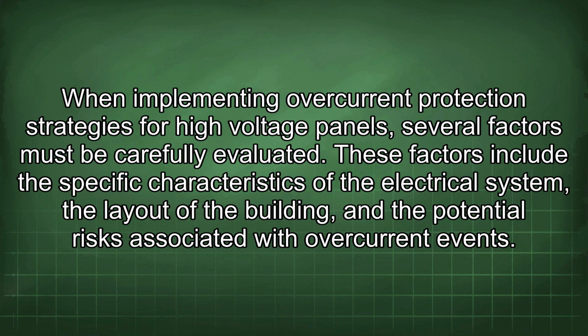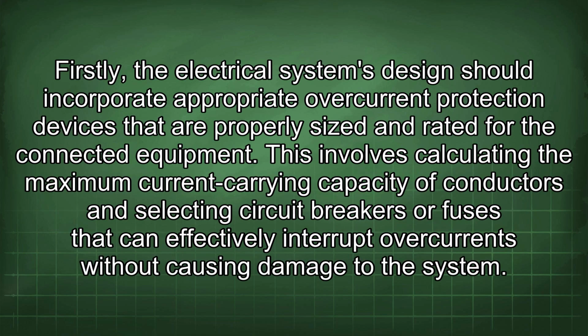Firstly, the electrical system's design should incorporate appropriate overcurrent protection devices that are properly sized and rated for the connected equipment. This involves calculating the maximum current carrying capacity of conductors and selecting circuit breakers or fuses that can effectively interrupt overcurrents without causing damage to the system.